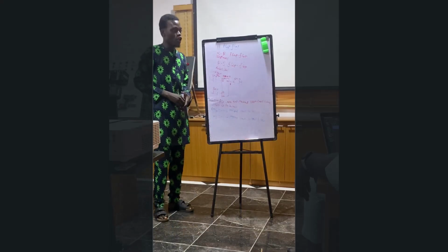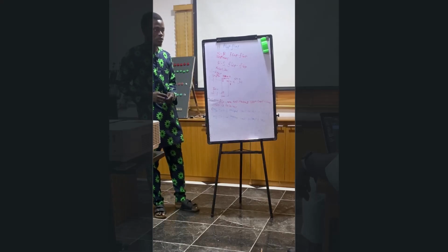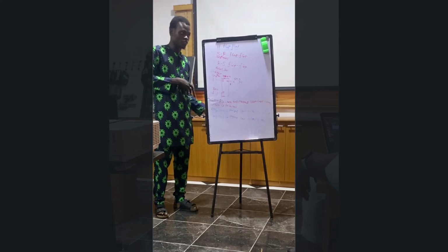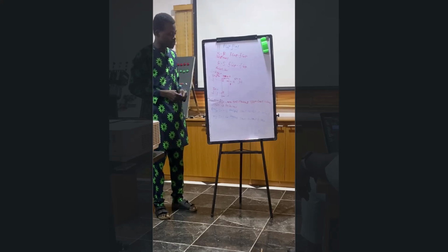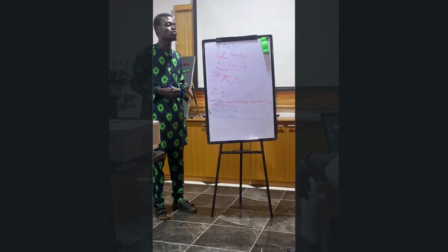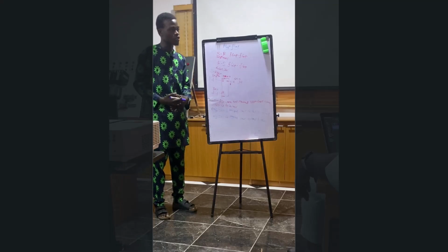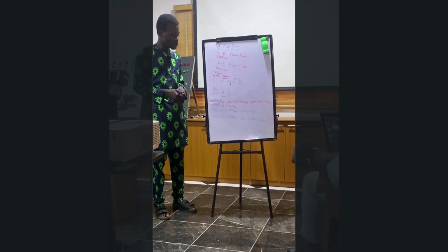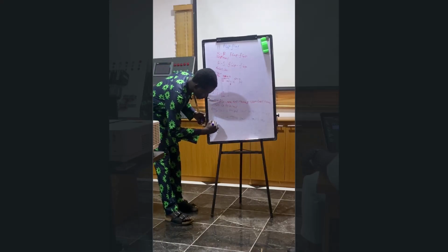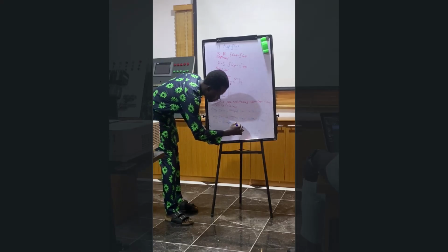So what will happen if we press the two? In theory, but in PLC programming now, in TIA Portal to be precise, one will have higher priority over the other. One will dominate the other. In the case of SR flip-flop, reset dominates set.